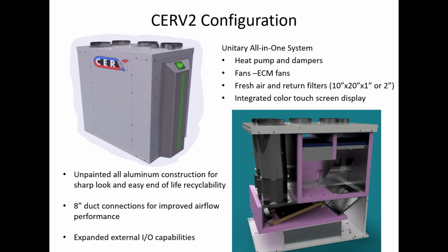The connections are all 8-inch, so these are nice large duct connections to reduce pressure loss, reduce any noise, trying to keep airflow noise down, reducing fan power as well. And then on the CERV2, we've expanded the capabilities from an I/O input-output standpoint, so interacting with outside devices and capabilities.